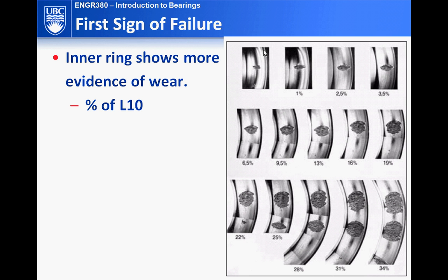Now, how do you know that such a thing happens? Because this usually happens inside the bearing. Unless you do regular maintenance, where you take everything apart and make a visual observation, you can go by listening to the operation. If you hear some clunking noise or some squeaking noise, that usually means there's something wrong inside the bearing. When that shows up, you can also see that as your first evidence of a failure, right?